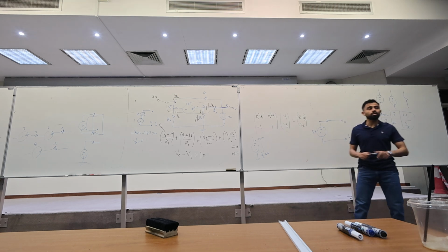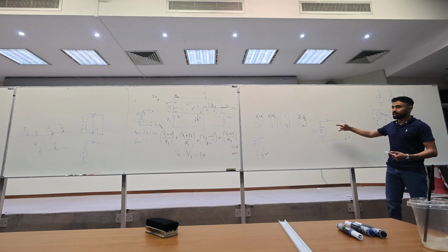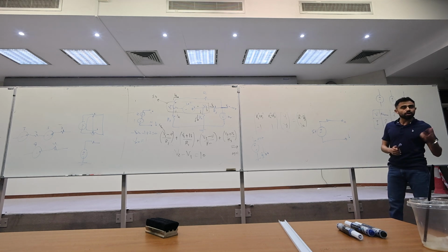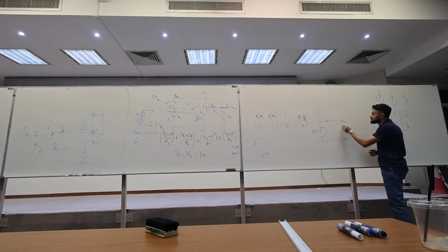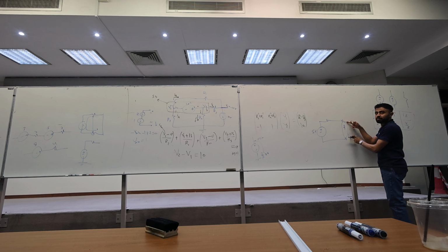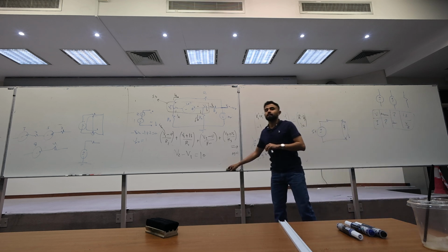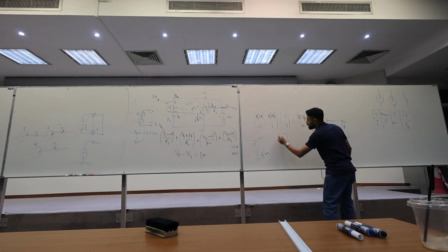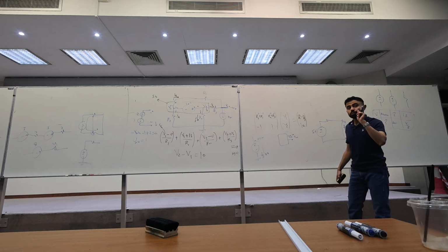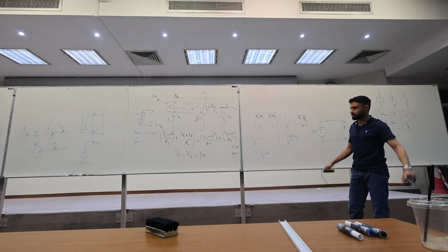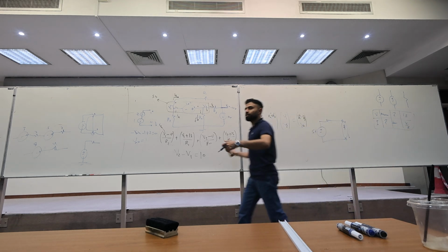You need to close it. Now when we apply our Thevenin, the way it works, you put a fake system, which is the ohmmeter. When you put the ohmmeter you close the circuit, so there is current flowing and you see the R Thevenin. But with an open circuit, when you see a two terminal device AB, the current I equals 0 for V open circuit always. When you put R Thevenin it's another story. I'll explain it. Now let's start with the source transformation.